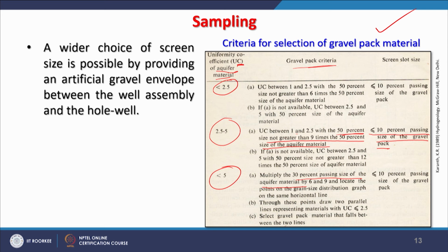Otherwise, when you pump out the water, that material will also come. But material may not be a problem, we can filter it, but that means it is doing scouring in subsurface conditions, and after some time the well might fail, and therefore the larger materials should be kept outside the screen, and that can be only controlled by this uniform coefficient or the screen size, better.